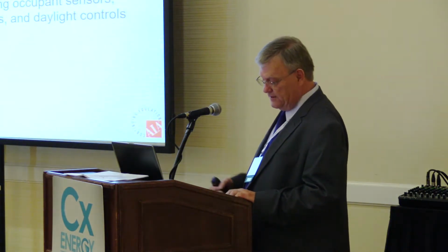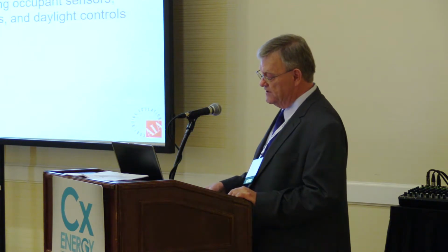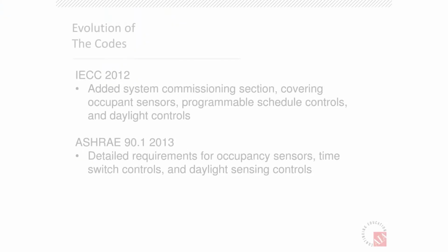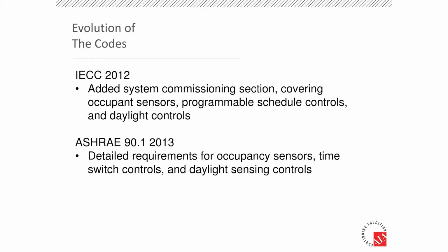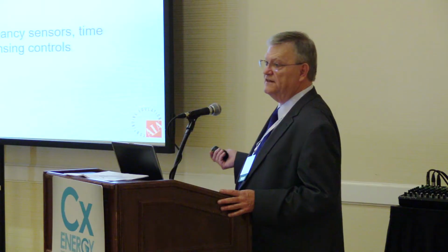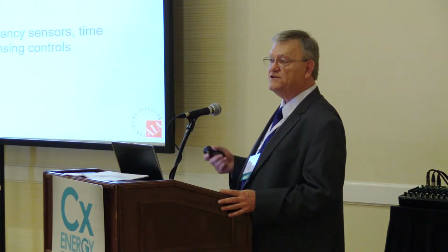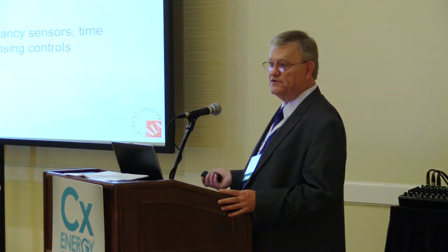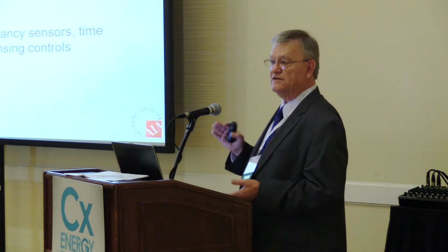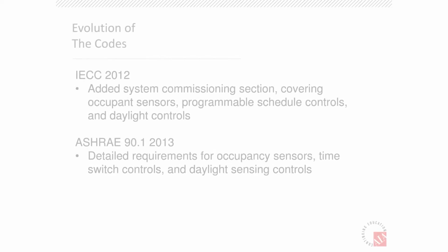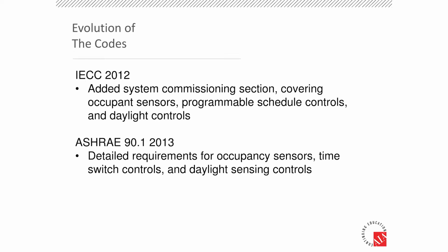Finally, and then confirm that photocell sensors actually work. 2012, we got a system commissioning section in IECC. We don't have that in ASHRAE. We have a requirement for functional testing, but IECC has a section dedicated to system commissioning that covers occupant sensors, schedule controllers, and daylight. It's a fairly detailed set of requirements.